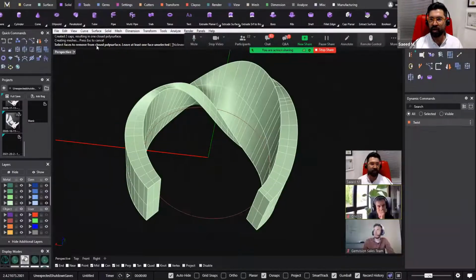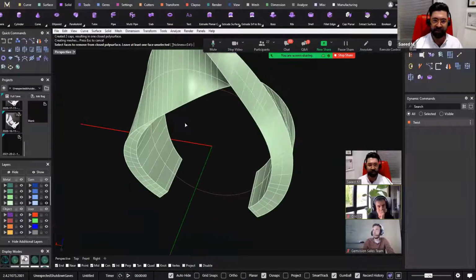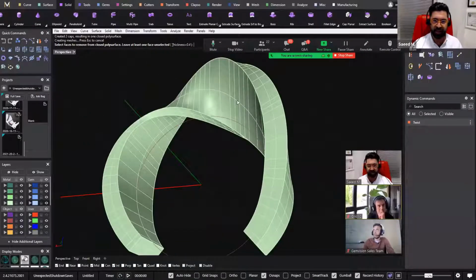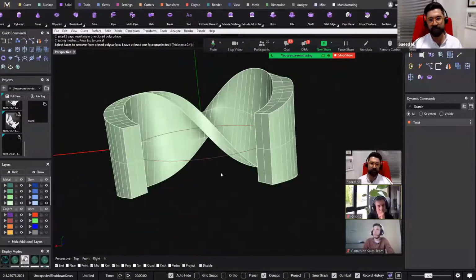And for this kind of ring, this is a plain gold. There are no gems on this ring. So when we talk about the wall thickness of the gold, it depends on whether you want to do direct casting, or make a rubber mold, what kind of diamonds or gems you have in your rings, and it depends on the diamond setting method. You can increase or decrease the wall thickness of the gold.